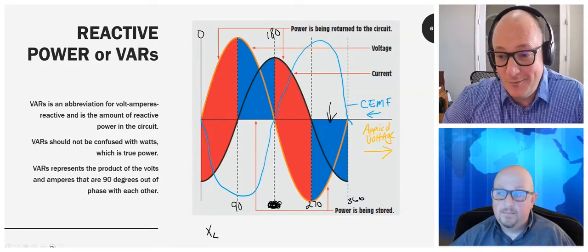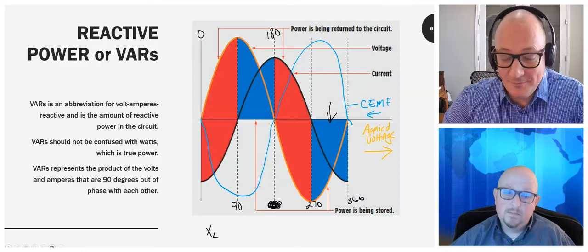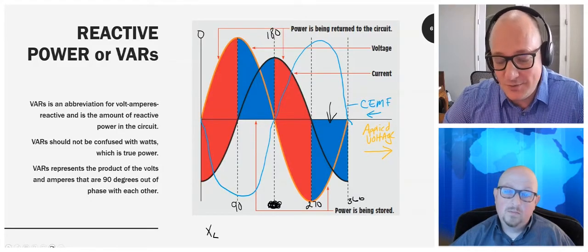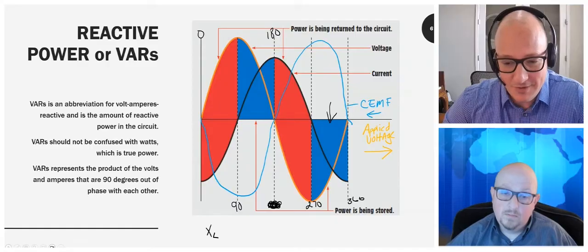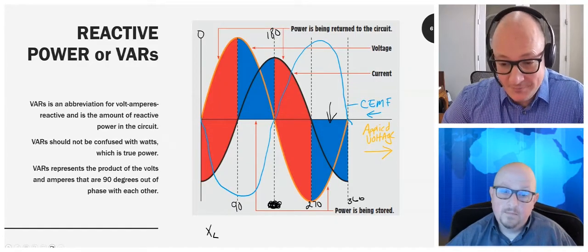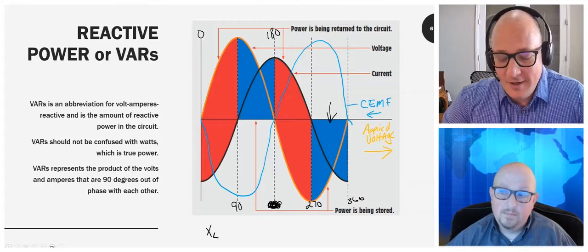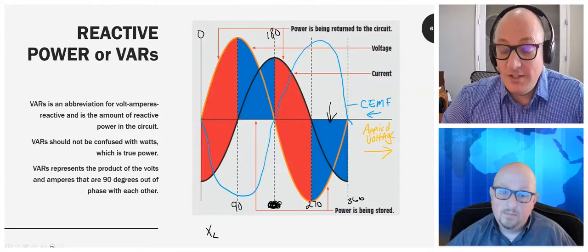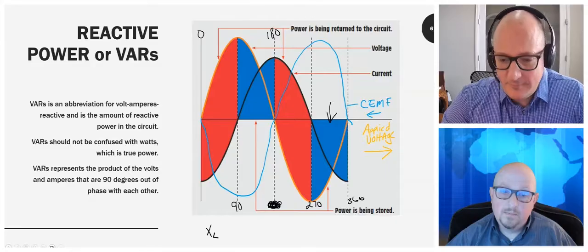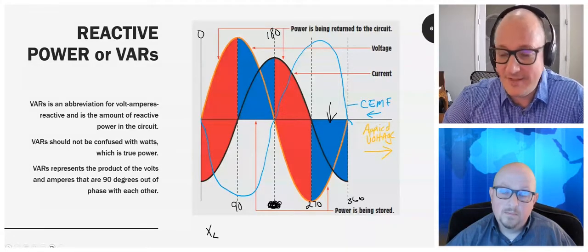We call it apparent power, but you don't get something for nothing, right? You have to put in. The voltage is fixed. The utility does a good job keeping voltages where they need to be, so we're always just going to use nominal voltages. Everything's perfect. Well, I have to put in so much current to get a certain amount of wattage out, because that's the reality. If I use these measuring devices and I see these transmission lines are really carrying a lot of current, but we're only getting this much true power out, that's not good for anybody, right?